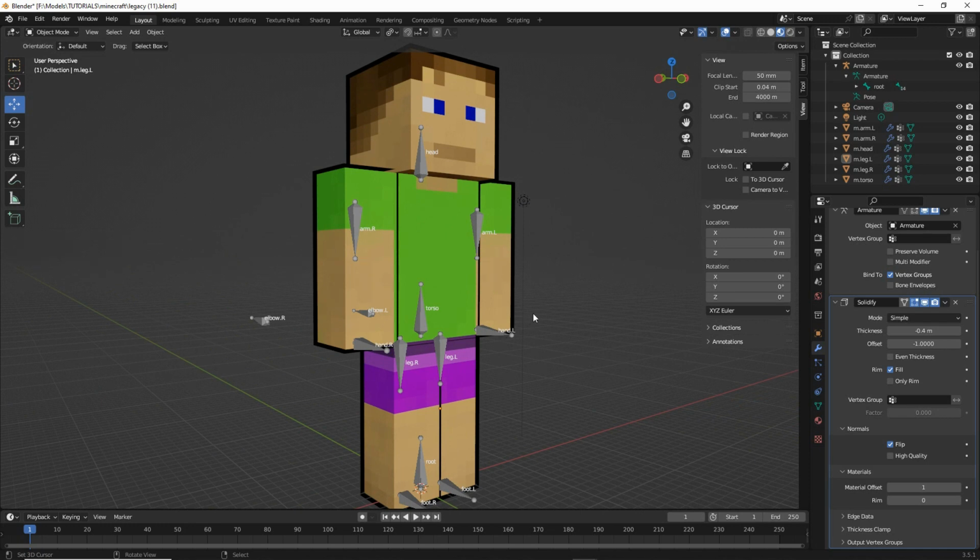Now obviously it has the same issues because it's not being post-processed. It's another cheap way of doing the same thing, but we've assigned them to our individual objects because we've kept the arms, well, the body parts, as separate objects. We could join all the objects together into a single mesh, and it would then just mean that we're creating a single instance of our solidify and a single instance of the material that's then assigned to the overall object.